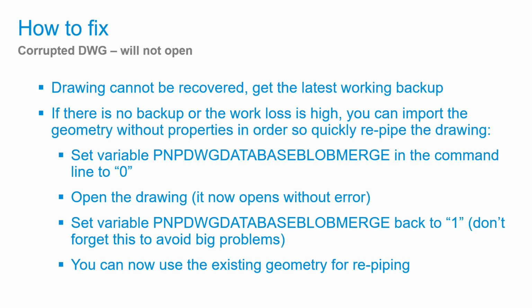And one thing you can do once you get it open is, there are times where you have to just reroute that pipe. So you may want to use a Navisworks coordination model as well. Bring it in, see where everything was, line that back up, and then repipe over. You can see what's missing and get that back in there, because sometimes this doesn't work. It's not a fail-safe thing.